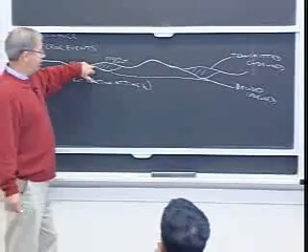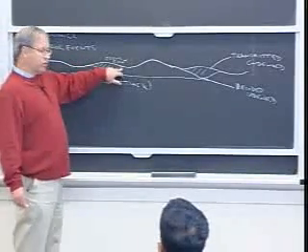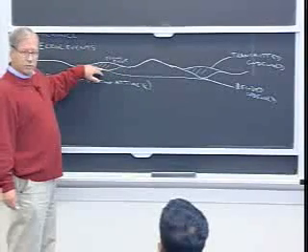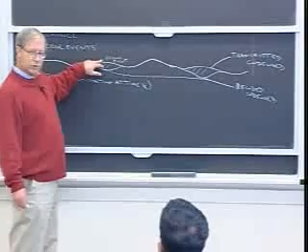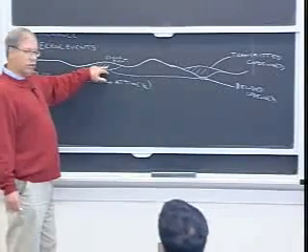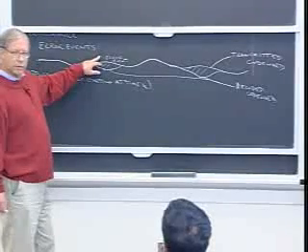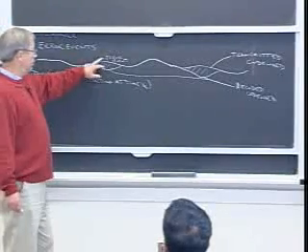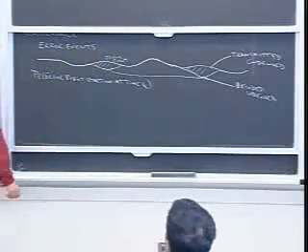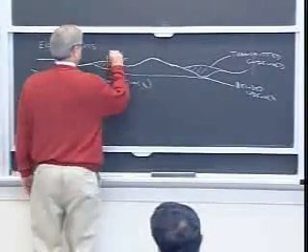What is the probability that this code word is actually more likely on a maximum likelihood sequence detection basis than this one? Well, simply the probability that the received sequence is closer to this one than this one. We know how to analyze that for finite differences.